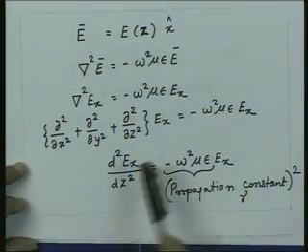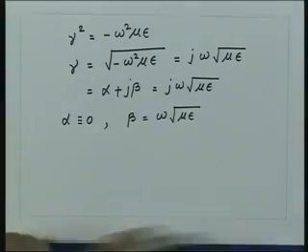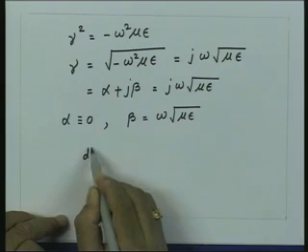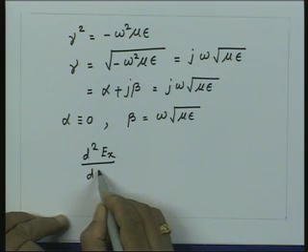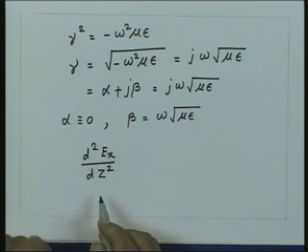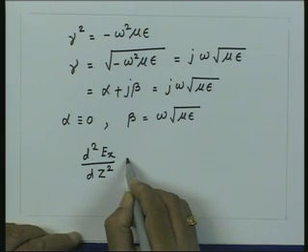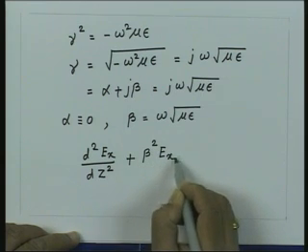And the solutions we got for the transmission line case were of second order differential equations. Once we define this parameter as the phase constant beta as we have done here, the solution can be written very easily. We can write the equation d2 Ex by dz square plus beta square Ex equal to 0.